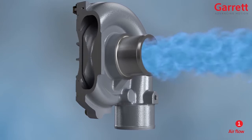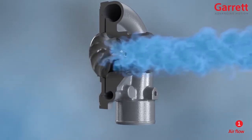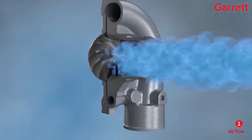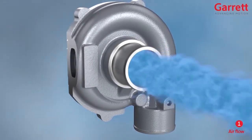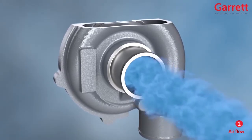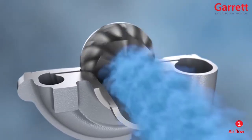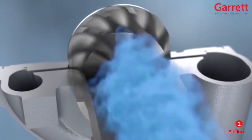The air passes between the blades and is accelerated up to extremely high speed. When working at high speed and load, the air passing through the compressor reaches a velocity close to supersonic. So now the air contains a lot of kinetic energy, which is energy due to motion. The next stage is where the compressor converts the energy from kinetic into pressure energy by slowing it down.